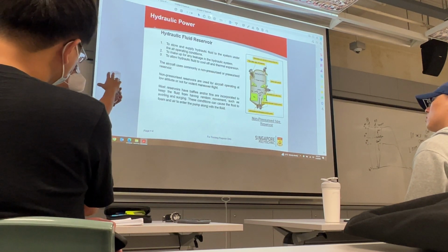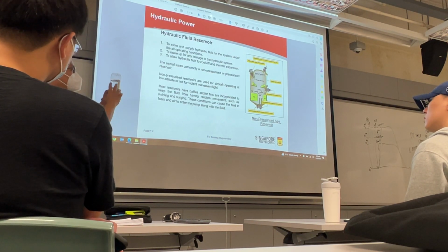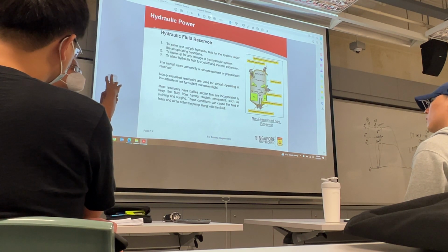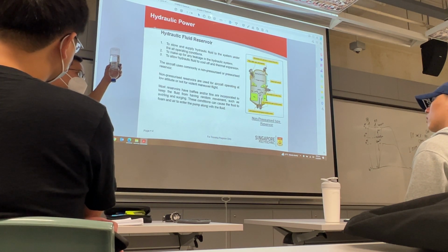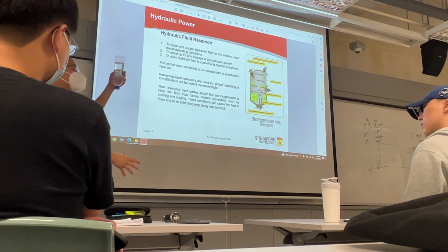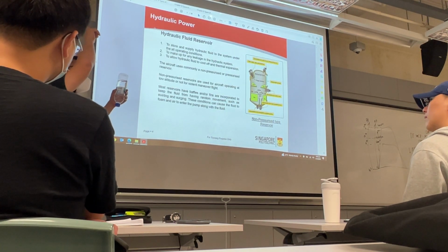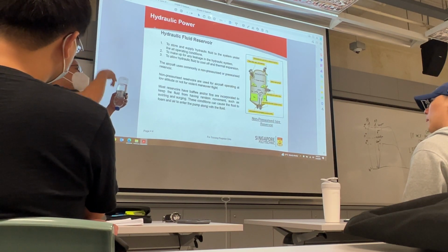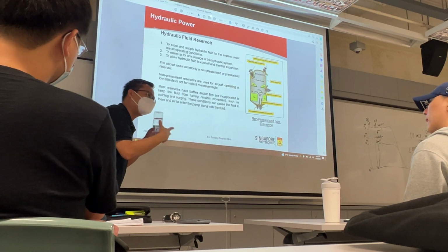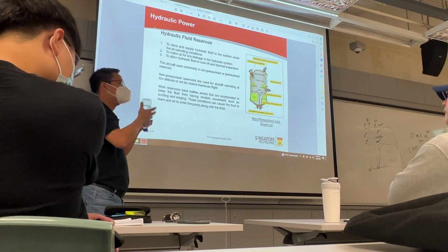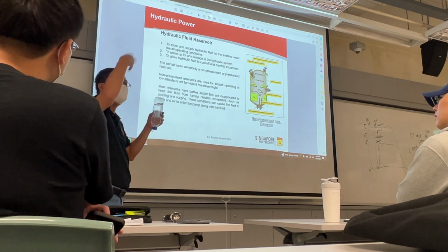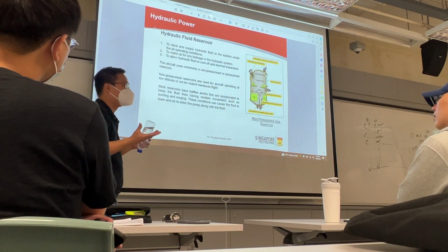What we are trying to achieve is to reduce cavitation regardless of whether it's non-pressurized or pressurized, by ensuring that reservoirs are usually placed at a higher height compared to the pump on the aircraft itself. Even our reservoir for the HDB water tank is at the rooftop. It's not to reduce cavitation; it's more to ensure there's gravity, so when you open your tap, you feel a very strong supply.